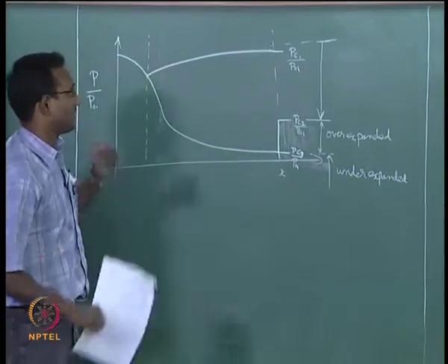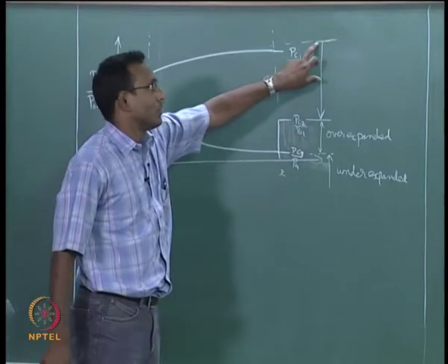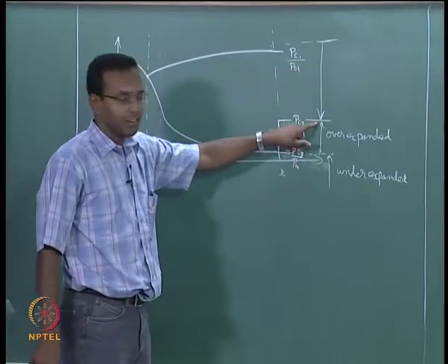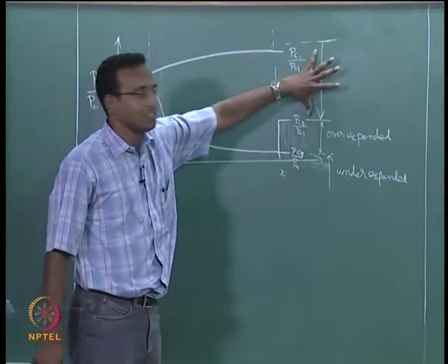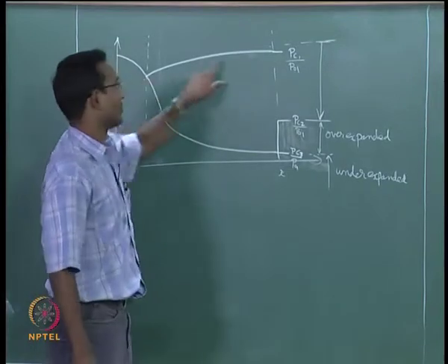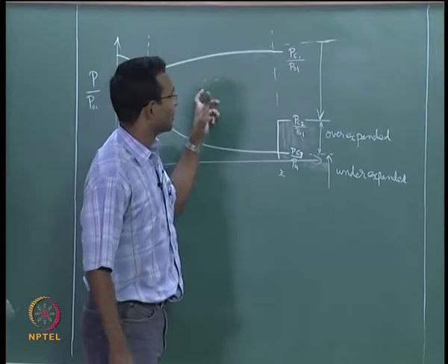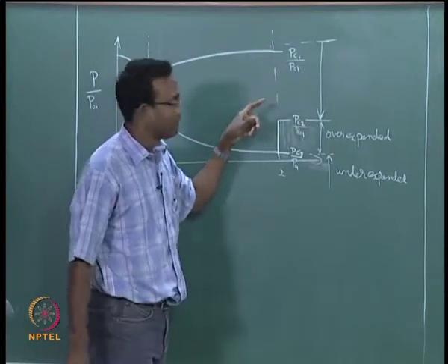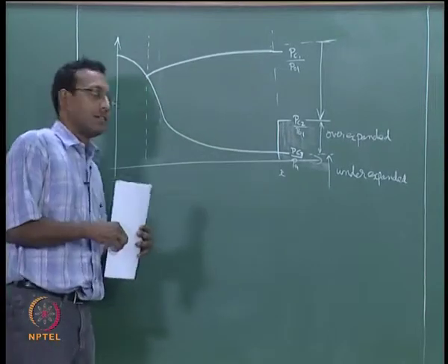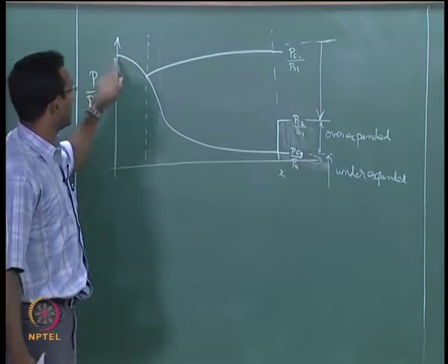Anyways, so from Pb equal to P01 all the way to Pb equal to P critical 2, everywhere I have already solved this, and we know that up to P critical 1 there will be no shock inside, completely isentropic. After that there will be a shock inside, and after that it will become subsonic and it will rise up to that pressure, and there will be a point where the shock comes to the exit. After that we said there is no change inside the nozzle.